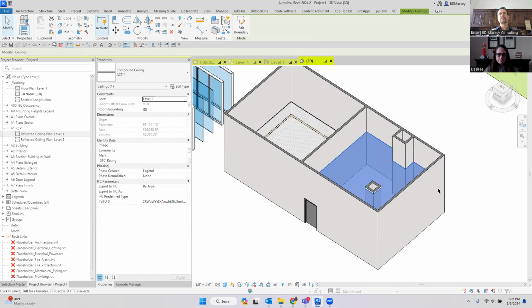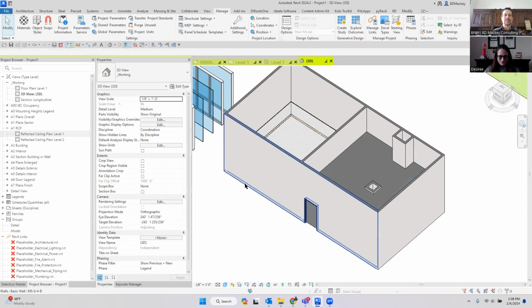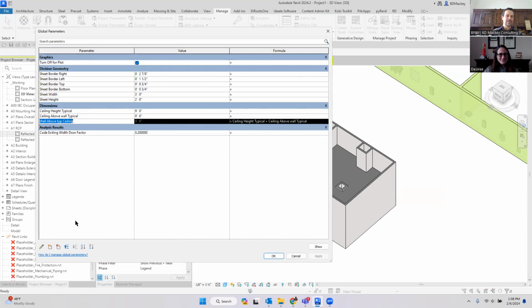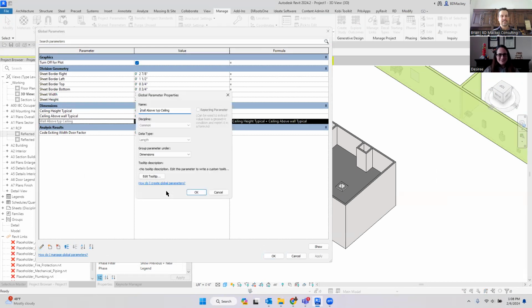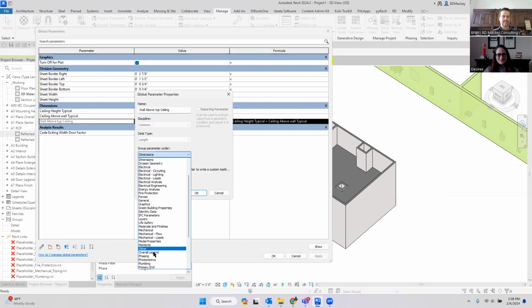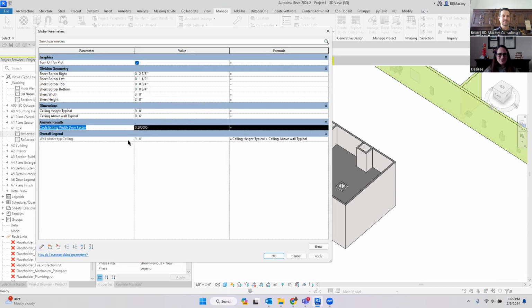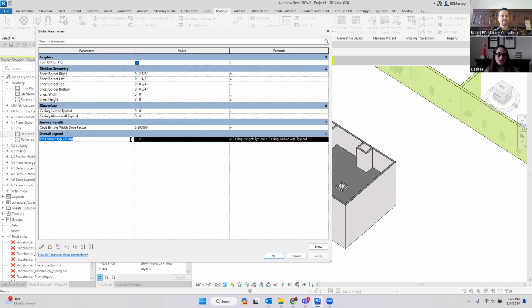It's just the other group. You can switch that parameter to anything but other. It's just other that won't let you do it. Oh, really? You're playing with that? Yeah. If I go to Manage, Global Parameters, and I say, cool, I want to take this one and change it to anything else. I tried Constraints and Fire Protection and a bunch of other ones, only other. That's funny. It's forcing you not to use other. I guess it just doesn't like the other.